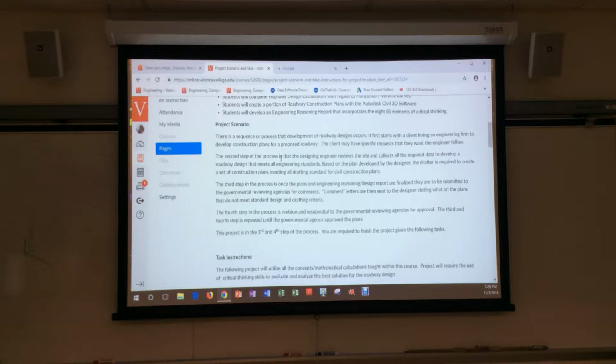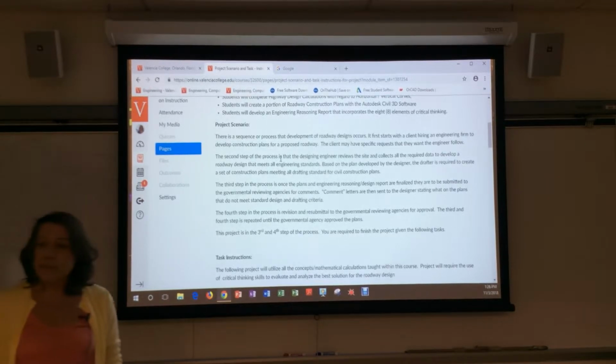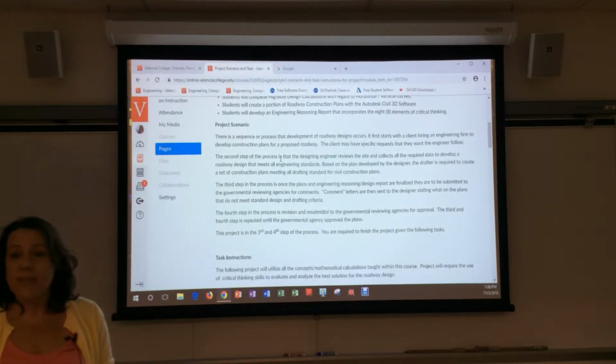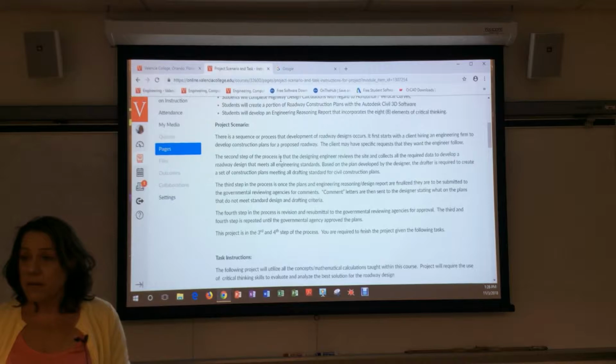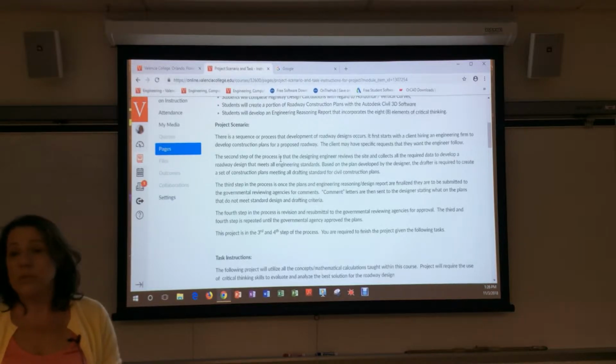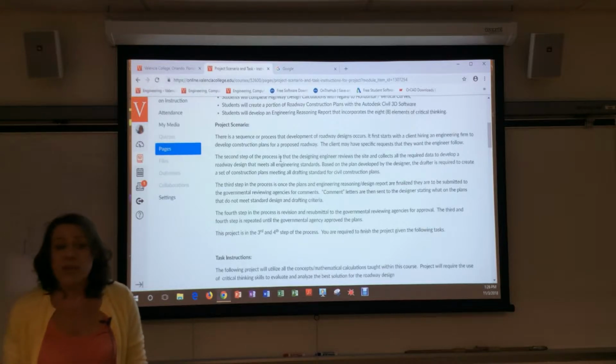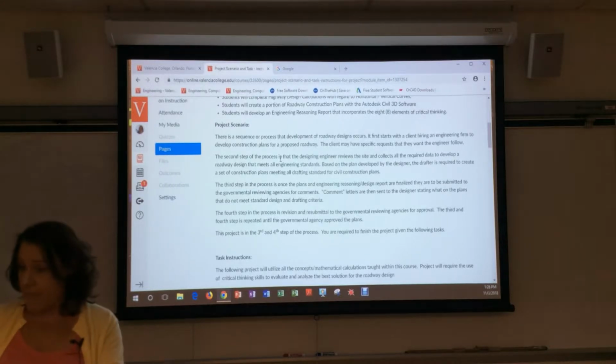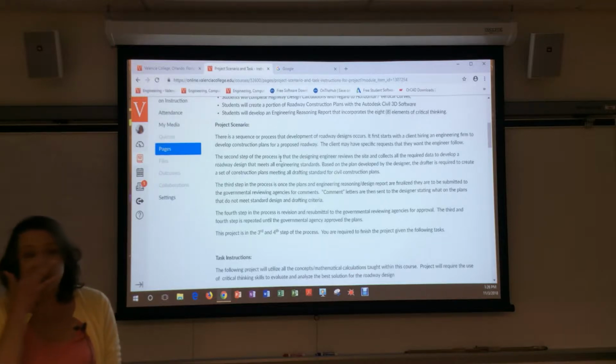Like I said, if we're designing for an industrial park and we're having semis coming in and out of there all day long, I'm not going to design a road that's only 10 feet wide. The tractor trailers will bump into each other. Their mirrors will clip each other. So even though the client wants a 10-foot wide road, as an engineer, you're going to be like, that's not safe. So you'll say, we're going to have to do this based on county code, standards, etc.